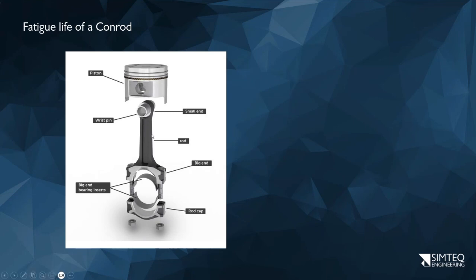As the engine speeds up, the stress dramatically increases. If I remember correctly, it's second order with a rotation speed. So driving, just looking at that load, 6000 RPM is 4 times as bad as at 3000.